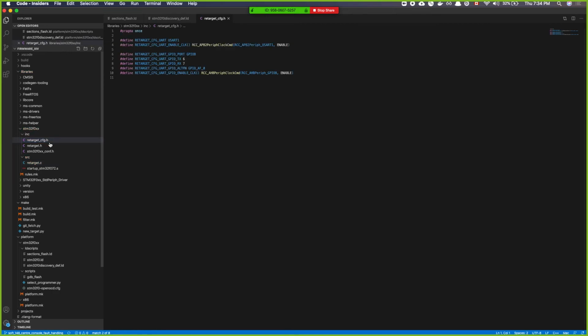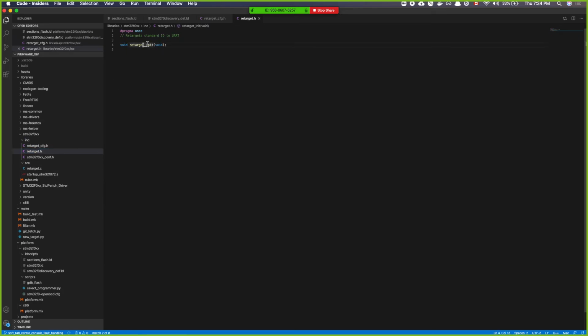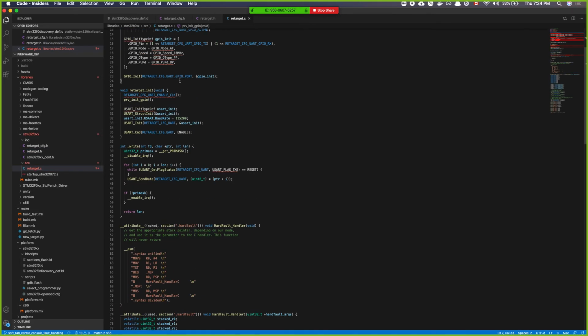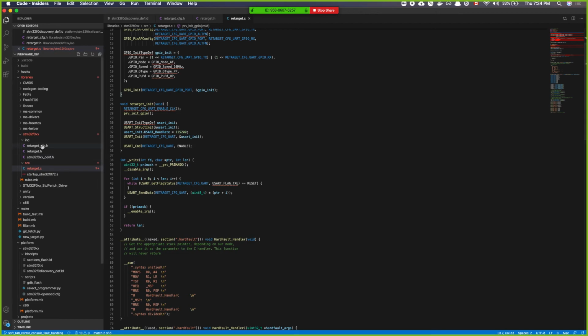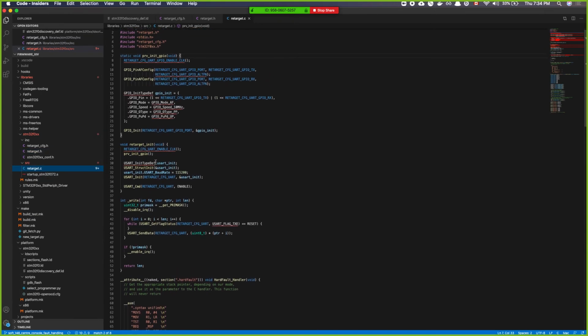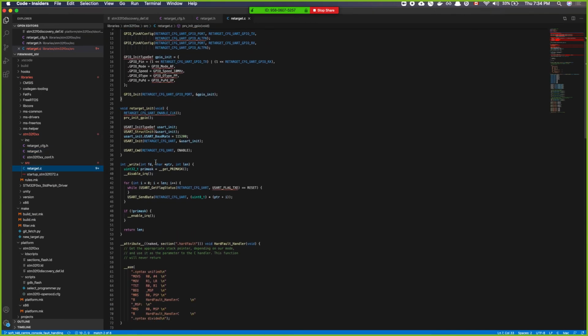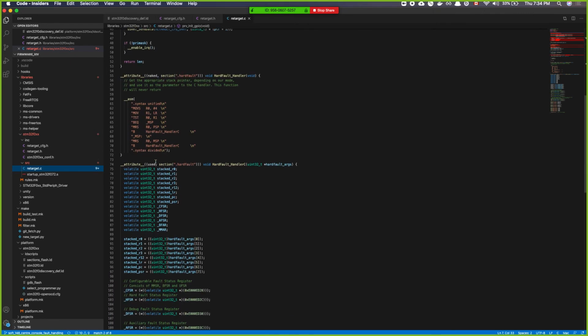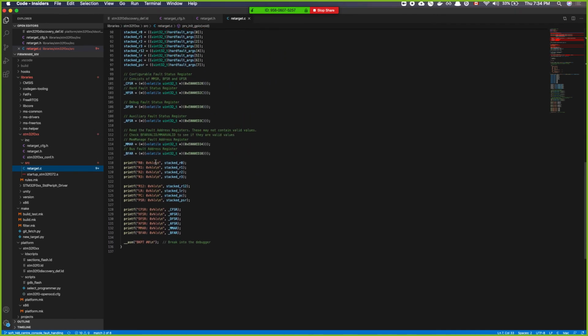And this is our retarget configuration file, so you can see the GPIO, TX, and RX. These are the clocks that we enable. In retarget.h, you just call this retarget init, making sure that our standard I/O is going to UART. If you read this, this is basically what that does. It says retargets stdio to UART, so your stdio will be sent out like that. So you pretty much define what printf does here, really.